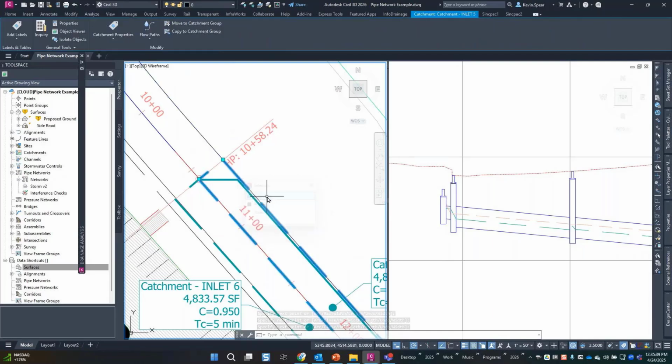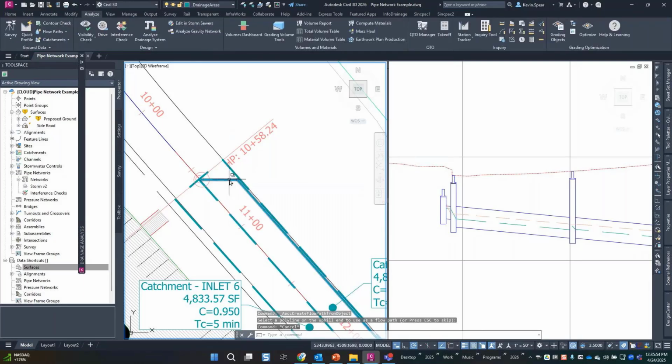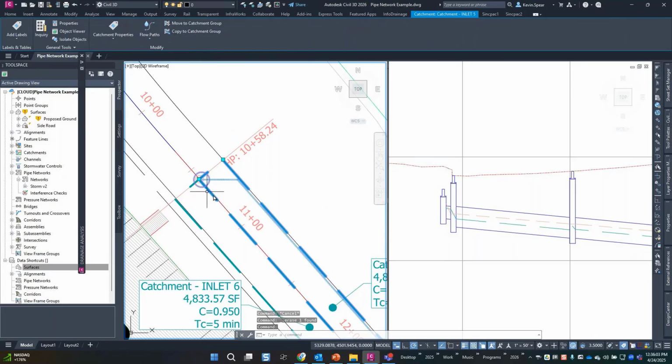So something like that, and then all the way down to the inlet. I'll come back to my catchment, create a flow path from object, and I'm prompted to select a polyline on the uphill end. I pick that. It's converted into the object, but the polyline is left behind, just so that we're not dealing with the wrong thing there. So there's my time of concentration path.